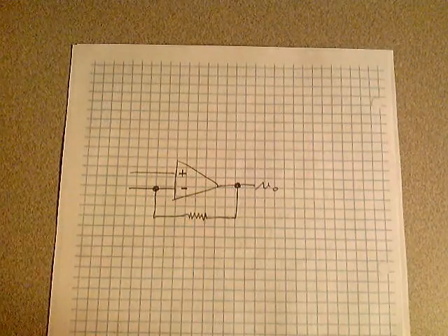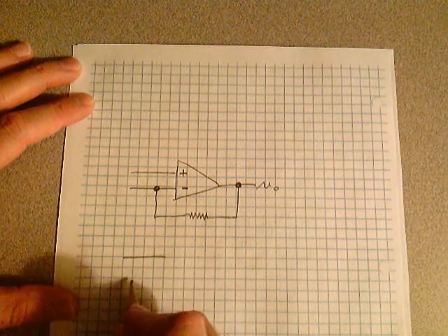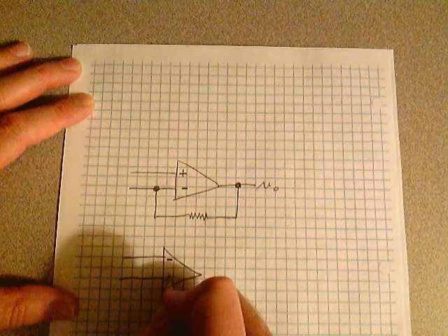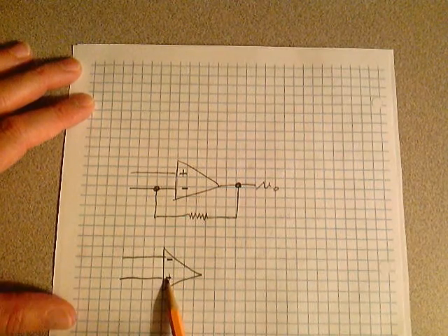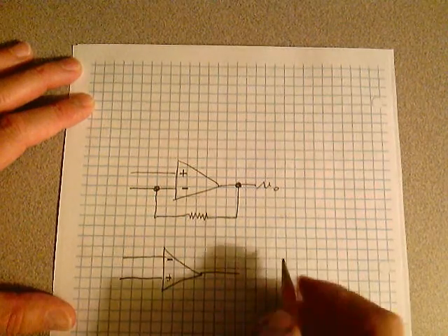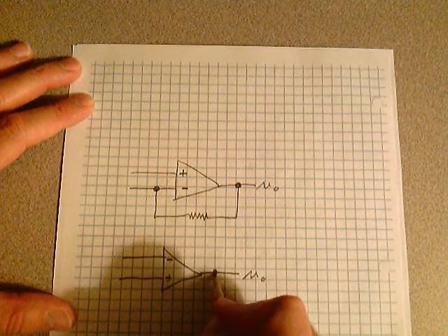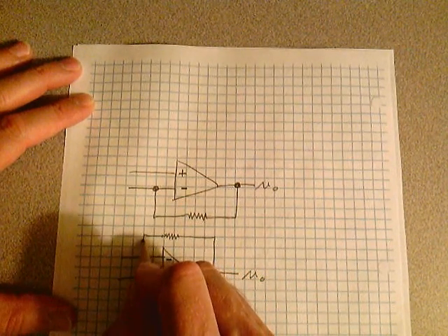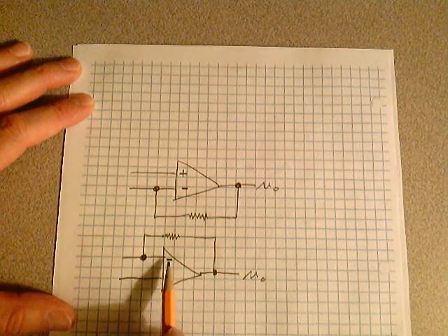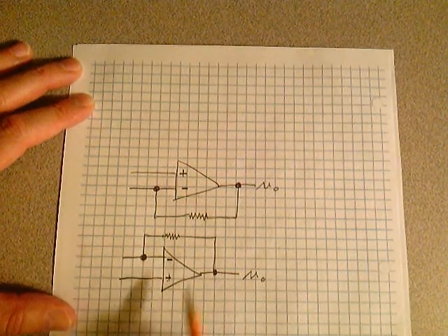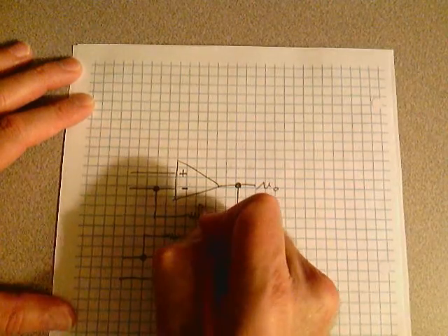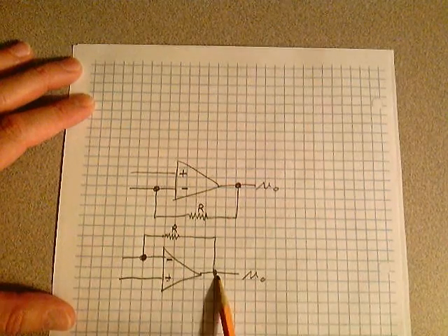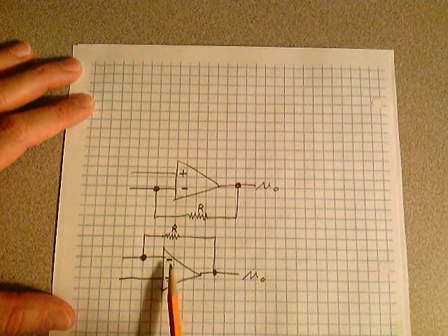That's how you're getting negative feedback. Now, I don't care if you do it this way or you draw your operational amplifier, and sometimes they put the inverting terminal up here and the non-inverting terminal down here. Here's your output here. If you take a portion of that output to a resistor, in most cases, not always, and you take it around to the inverting input or the negative input, that's negative feedback. These are the same circuits. They're exactly the same circuits. You just have these inputs switched. Notice the output goes back to the inverting input, the negative input.